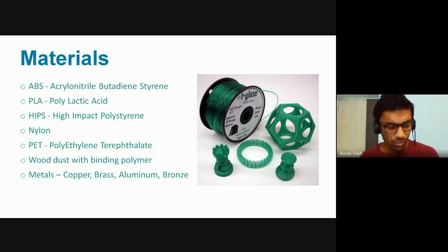The major disadvantage of using this PLA is when it is exposed to the environment, it absorbs moisture, and because of this moisture, the printed part loses its mechanical properties, and there are issues with the printing where the layer to layer adhesion is not very good.